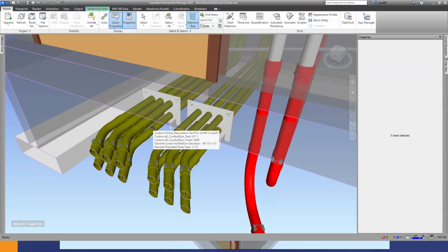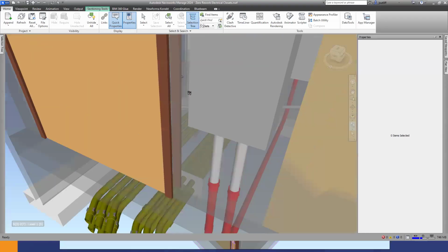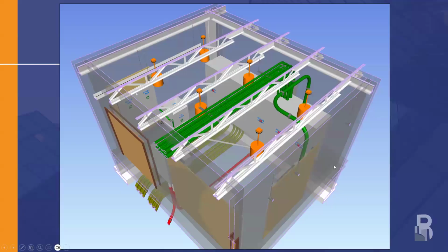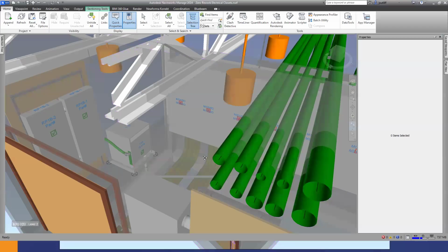And the properties look like it's not quite right, because the diameter trade size, even though it's a 4-inch PVC, says 3.5. So verifying that information is crucially important. Giving your field teams access to the model, and especially in the underground phase, identifying the elevation for them, will save a lot of questions.